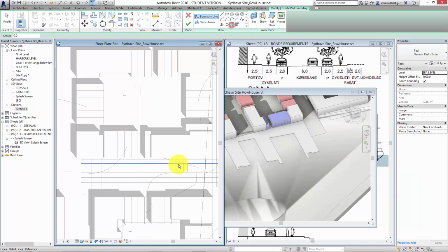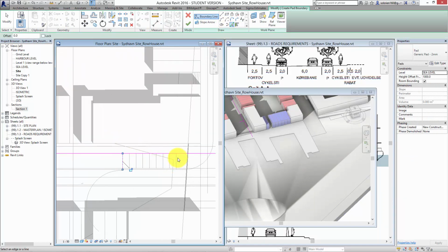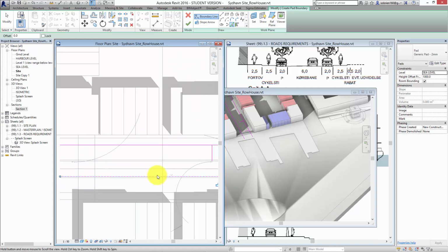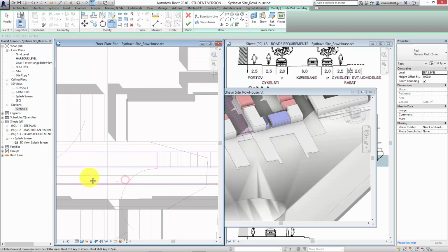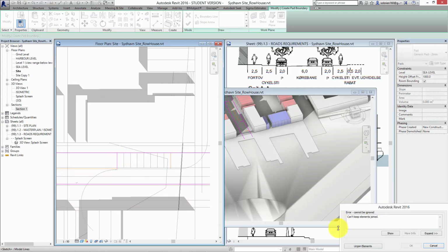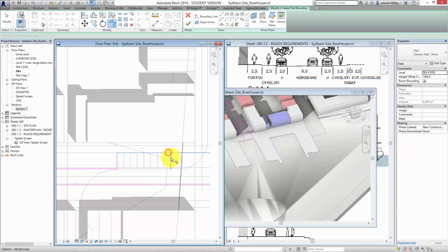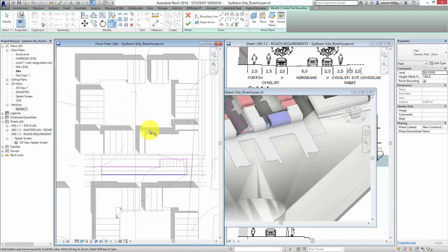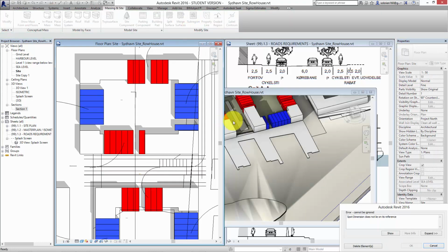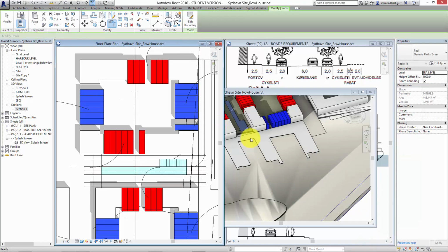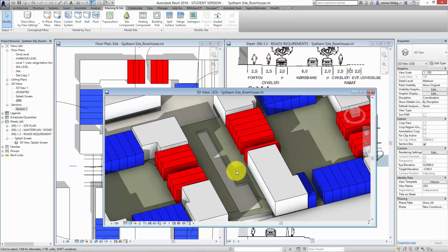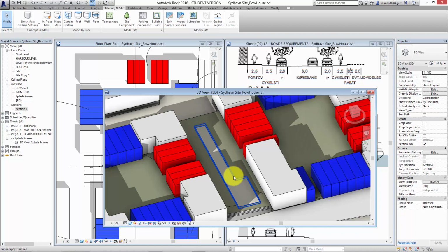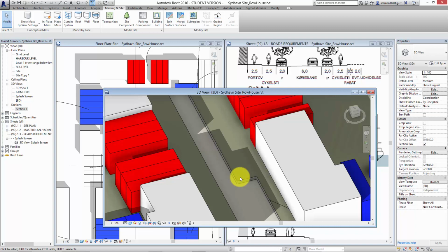Building pad, select lines, there, there, there, there, there, and then we'll just select this one, trim it together. Sea level plus 1000, accept it. And then you end up with something like this. So you end up with the equivalent of an excavation in the area that you want. And of course you can modify that and give it the curves that you necessarily need.